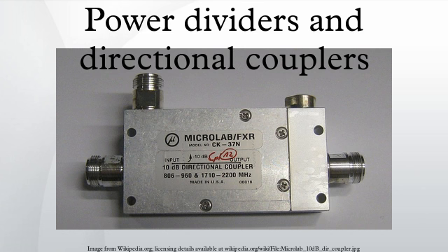In Figure 21, an example is shown of a signal split up to feed multiple low-power amplifiers, then recombined to feed a single antenna with high power. The phases of the inputs to each power combiner are arranged such that the two inputs are 90 degrees out of phase with each other. Since the coupled port of a hybrid combiner is 90 degrees out of phase with the transmitted port, this causes the powers to add at the output of the combiner and to cancel at the isolated port.